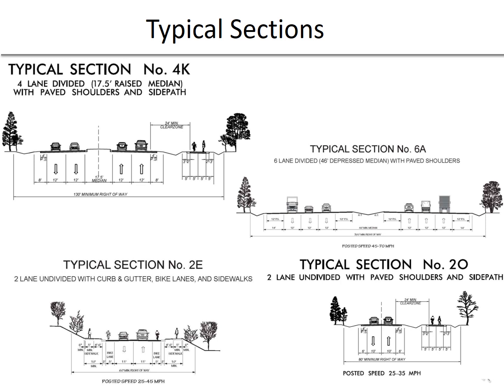Typical sections show the planned cross-section of a roadway from a general perspective. They show details such as widths for lanes and shoulders, slopes of pavement and ditches, and how the road will tie into the existing terrain. Typical sections give the general design of the roadway cross-section and are customized based on the needs at a particular location.